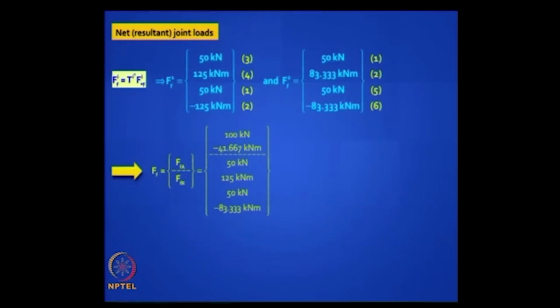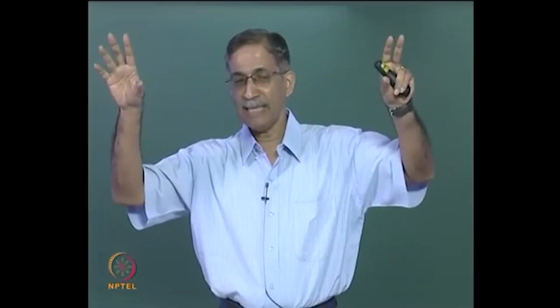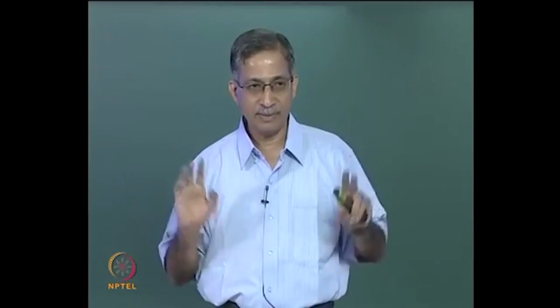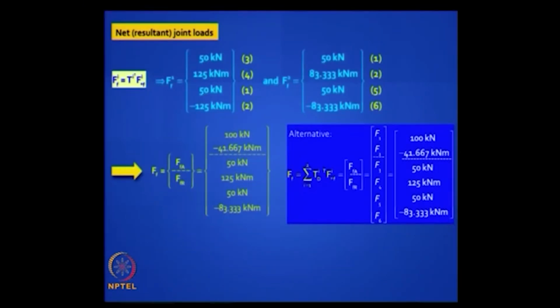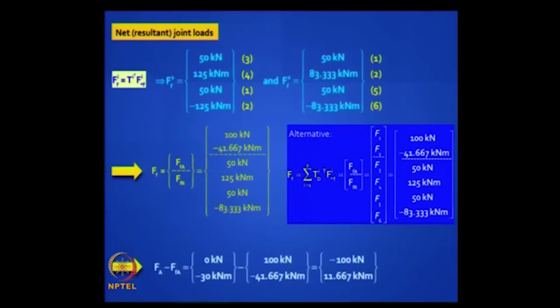This is a slotting thing, you have to put the right, once you have shifted to the global axis system, you are matching the element with the structure. Does it make sense? Clear? Okay. If you want to do the Td approach, that is straightforward. You got your Td, take the transpose, pre-multiply, you will get the same solution without doing any slotting. So this is in a sense easier, but you are dealing with bigger matrices, okay.